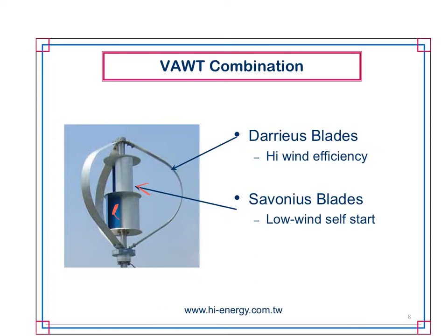At the higher speeds, you actually have the concept of lift that's getting that to rotate. So you're actually spaced out more, but that's because as the wind is impinging upon the blades, the wind's going to slow down, right? Energy is removed as you get those blades to rotate. So there's much more spacing, so these blades actually operate at a much higher efficiency at high wind speeds. They're almost non-effective at low wind speeds.